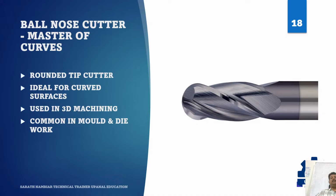Where do we see such surfaces? We see them almost everywhere, like mold cavities, die surfaces, automotive styling parts, aerospace shapes, artistic contours, impellers, turbine blades, any component where the surfaces are not simple straight walls and flat floors. And when CAM software generates 3D tool paths, ball nose cutters are often used for finishing because the rounded tip can smoothly travel across the changing slopes.